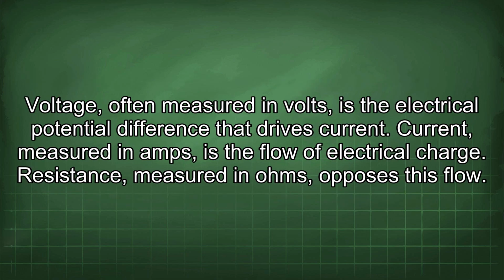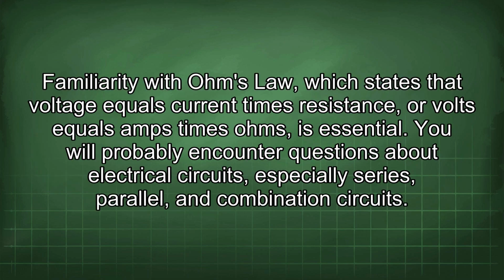Basic electrical concepts will likely be tested, so a solid grasp of voltage, current, and resistance is paramount. Voltage, often measured in volts, is the electrical potential difference that drives current. Current, measured in amps, is the flow of electrical charge. Resistance, measured in ohms, opposes this flow. Familiarity with Ohm's law, which states that voltage equals current times resistance, or volts equals amps times ohms, is essential.